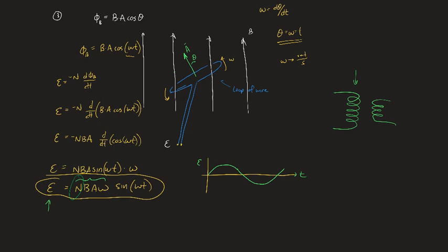And we'll be able to describe this, but these are called step-up transformers. It is very likely your car had one. A lot of them don't anymore, but older cars do. My car still does. It's a way of generating enough voltage to get sparks in the engine. You only have a 12-volt battery. That's not enough to generate sparks. But using a step-up transformer, you can ramp up the voltage so the spark plugs will fire. It's a simple way of changing voltage.